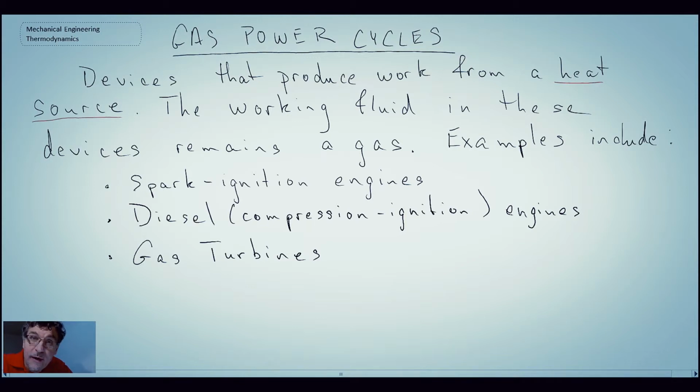Those are gas turbine engines, and they provide the propulsion for the aircraft when it's flying, but they're also used for other applications, like gas transmission pipelines for power production. Typically when you're above about the 30 megawatt range, that's when you get into gas turbine engines. They're also used for stationary power production, peaking power for electrical utilities, things like that.